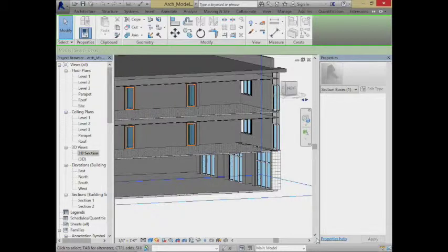And the reason sanitary systems are so hard to design is they tend not to have a lot of back pressure. We don't put a lot of pumps into them. We try to use gravity to basically let everything flow downhill. So sanitary systems, the pipes all have to run downhill at a very specific slope.